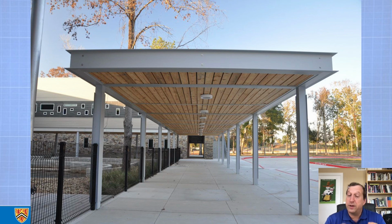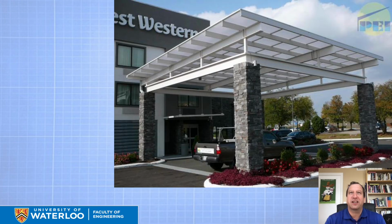In this case, we could have a moment frame to make this canopy and walkway entry. But when we look at this example of a canopy, that very likely is relying on moment resistance of the vertical posts to allow this slender beam in between. But it would be either a rigid frame or a cantilevered vertical post or some combo.